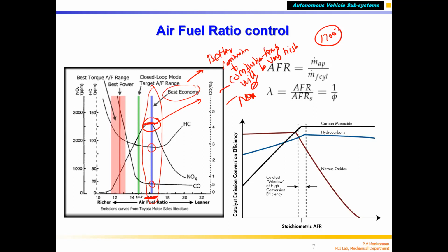rises. Correct. It will go from around 200 degrees before combustion to around 1200, 1000 also. During the combustion power stroke, when fuel is burning, when the combustion temperature increases to around 1200 and above, correct, the NOx, nitric oxide, is very high, correct. That happens only when the air fuel ratio is maintained around 16.